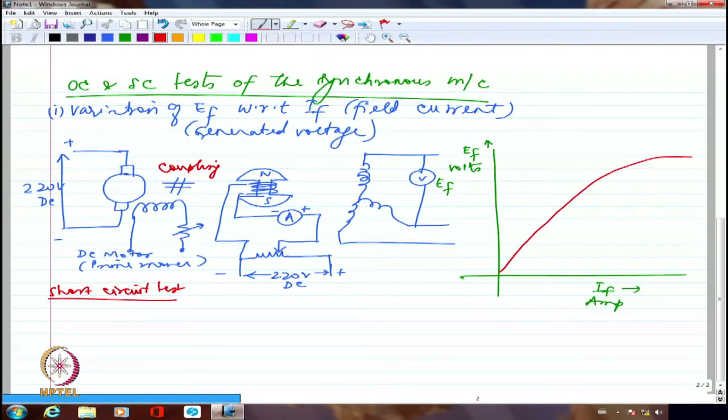So synchronous motors are essentially constant speed motors. They will not even have the small variation that is seen in an induction machine. No way. There will not be any change. So if I want to have speed control, I have to have frequency control. No wonder we have become a very important commodity, power electronic engineers, who make inverters, who basically generate variable frequency. So all the synchronous motors are now able to run at variable speed if I am able to generate variable frequency. That's the reason.